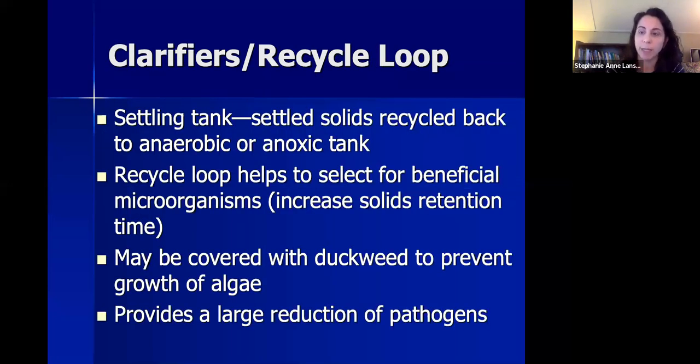So after the planted aerobic tanks, you're going to go to a settling tank where the settled solids can be recycled back to an aerobic or anoxic tank. And that recycle loop helps to select for beneficial microorganisms and increases the solid retention time, so we get more treatment within the system. Instead of just settling out the solids in a normal wastewater treatment system, where those solids are biosolids applied to a field,